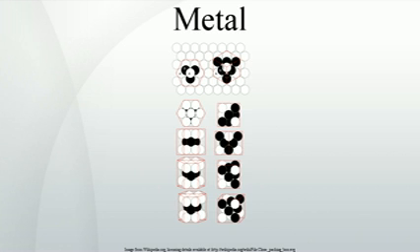The oxides of metals are generally basic, as opposed to those of nonmetals, which are acidic. Blatant exceptions are largely oxides with very high oxidation states such as CrO3, Mn2O7, and OsO4, which have strictly acidic reactions. Painting, anodizing or plating metals are good ways to prevent their corrosion. However, a more reactive metal in the electrochemical series must be chosen for coating, especially when chipping of the coating is expected. Water and the two metals form an electrochemical cell, and if the coating is less reactive than the coatee, the coating actually promotes corrosion.